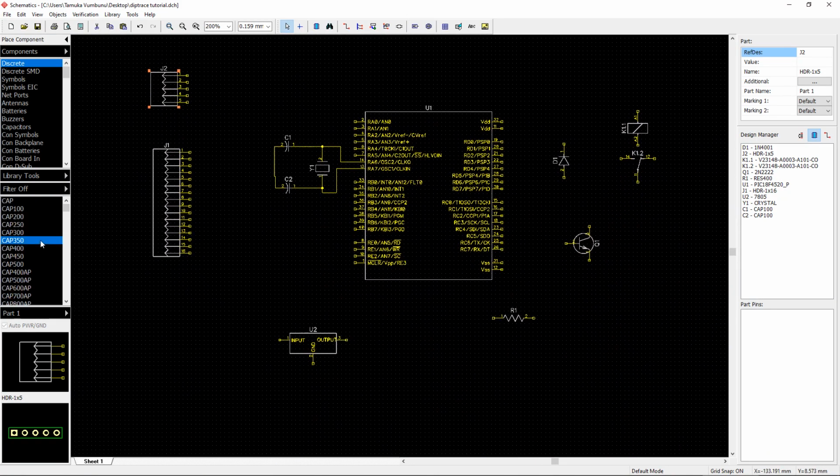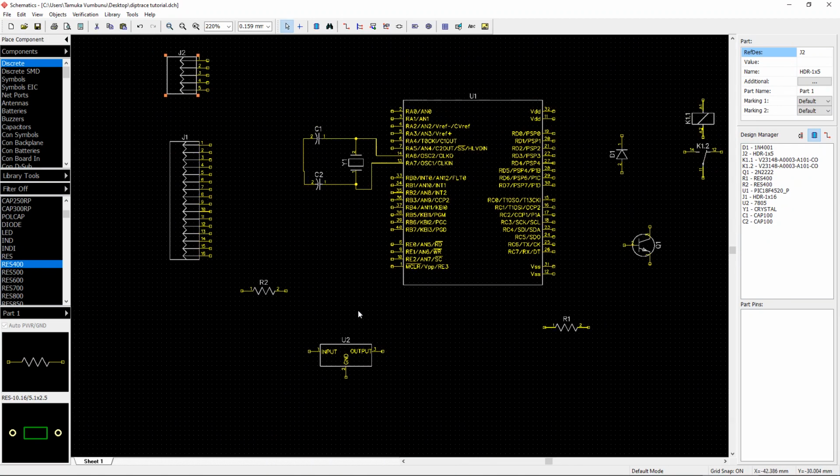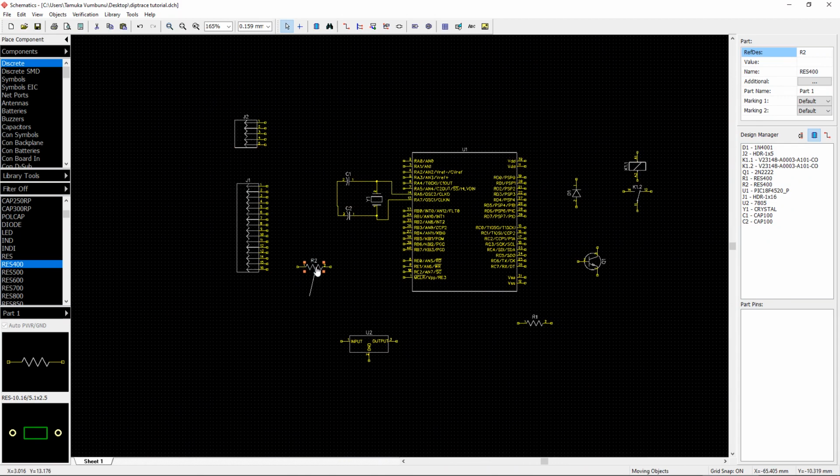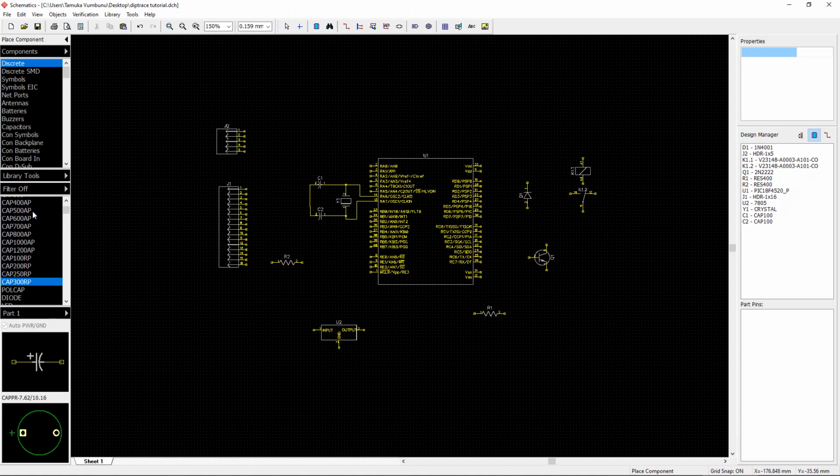Okay, so what's next? We also need a resistor. We need a resistor for pulling the anode, like for dropping the current to the LCD backlight. We use that anode. Okay, we also need capacitors to smoothen out the DC transients, should there be any, from our power supply through our linear voltage regulator. So just 2 of them will suffice, I think.